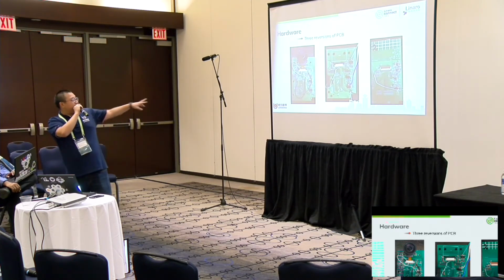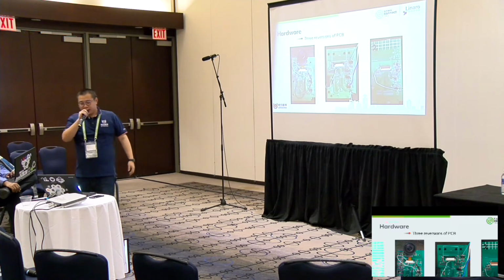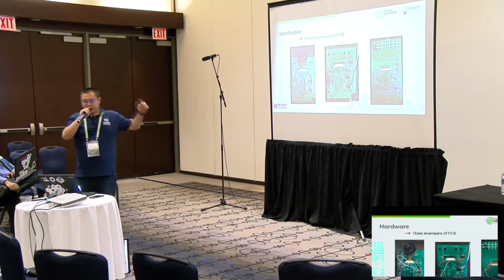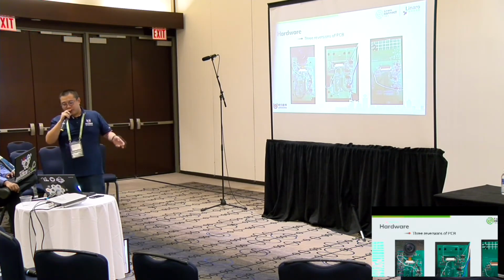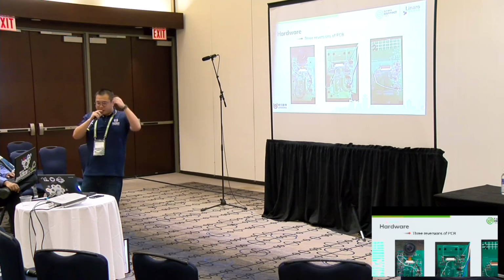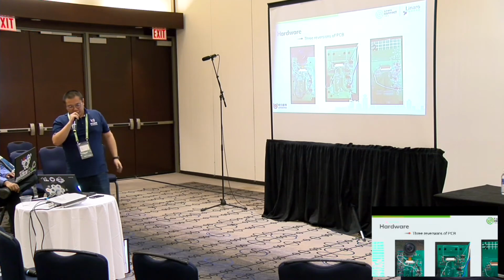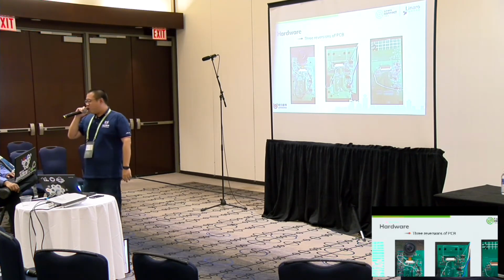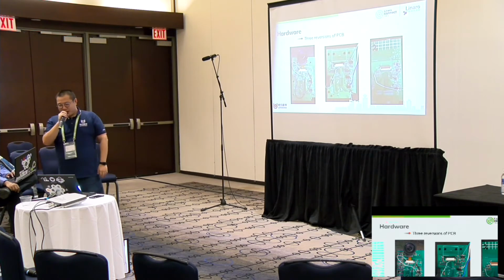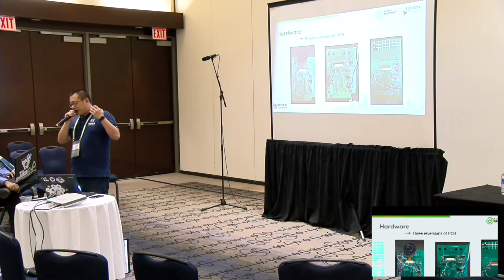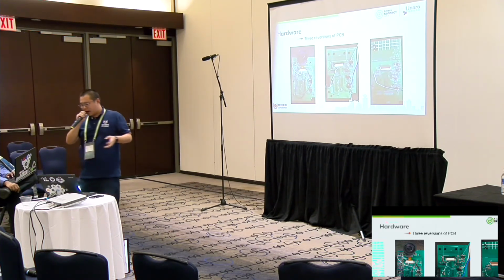So we connected the 2 lanes of I2C in the second version, and it works, but it doesn't work so well. So we made the third version, but I don't know if it is because of a problem with the connector. The third version is not working at all. So we would like to make the 4th version to see if it is a design problem or a hardware problem.